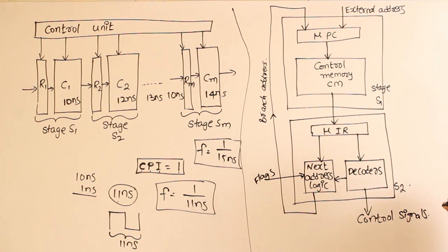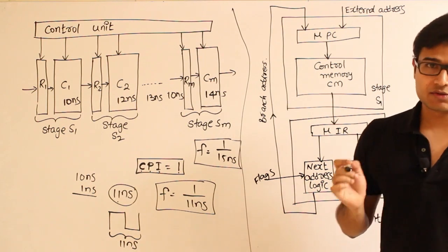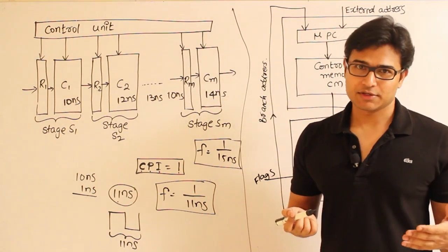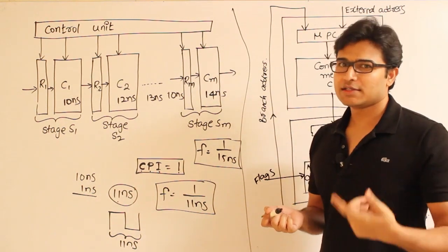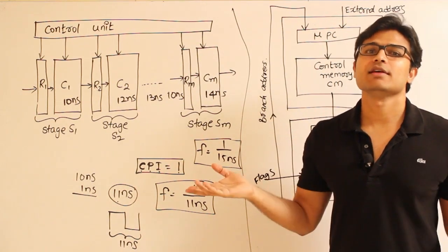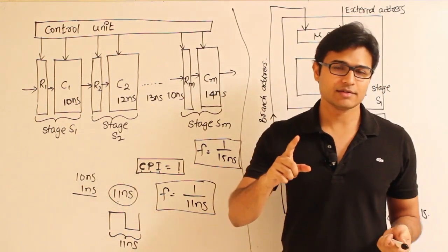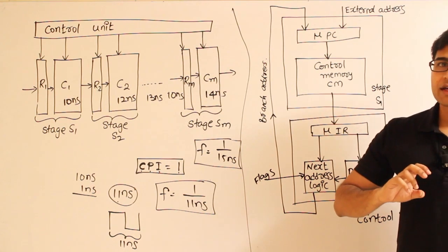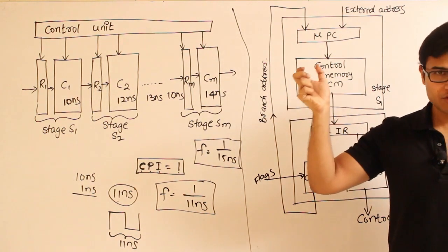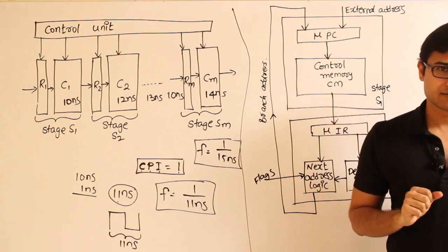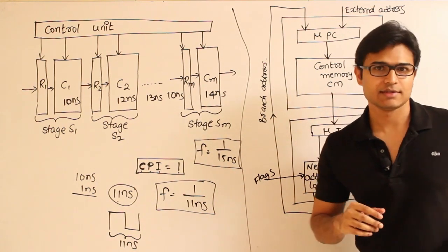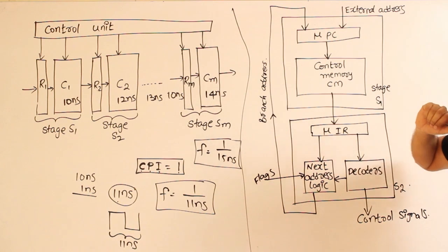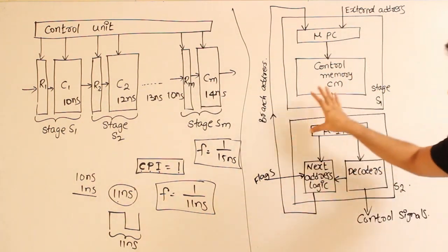Now if you remember, we have discussed micro instructions. In the case of micro instructions, the best thing is we don't have to execute the instruction. We just load it into the register and automatically the decoder is going to generate the signals. We have already seen this while discussing the hardware design. Now assuming that we have such a micro programmed control unit, we are trying to pipeline that one. Since this is the basic smallest example, I took this. You need not memorize it, just try to understand how it is implemented, right? This is the generic one and this is the practical one which we are trying to implement.